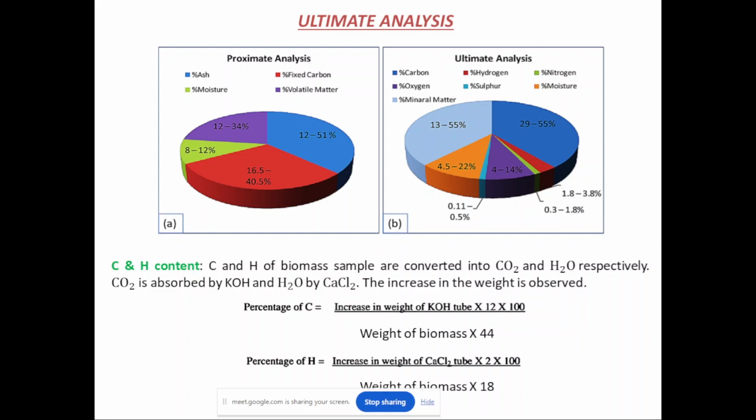Remember, the word stoichiometric is important, because if you react the biomass sample with a limited supply of oxygen, it will result in incomplete combustion, forming CO, carbon monoxide. Only when the oxygen supplied is in excess or in stoichiometric ratios will complete combustion happen, with carbon reacting with sufficient oxygen to produce carbon dioxide.